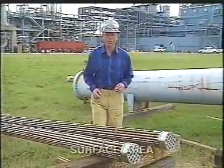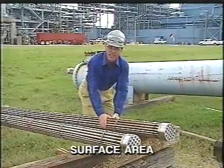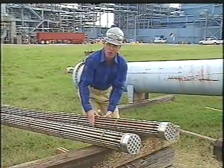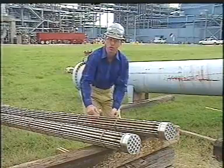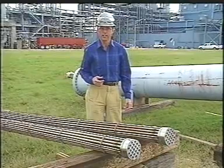To ensure a large surface area, most heat exchangers have a system of tubes inside. The liquid in these tubes is referred to as tube side flow. Another liquid is directed through the space around the tubes. This is called the shell side flow. By having many tubes, more heat can be transferred.